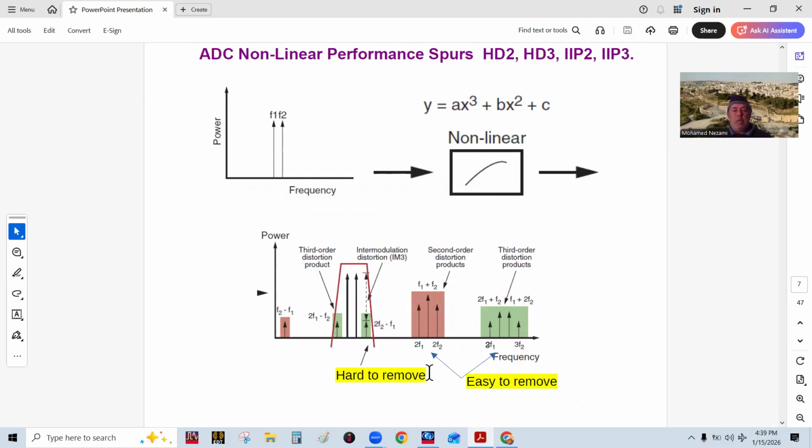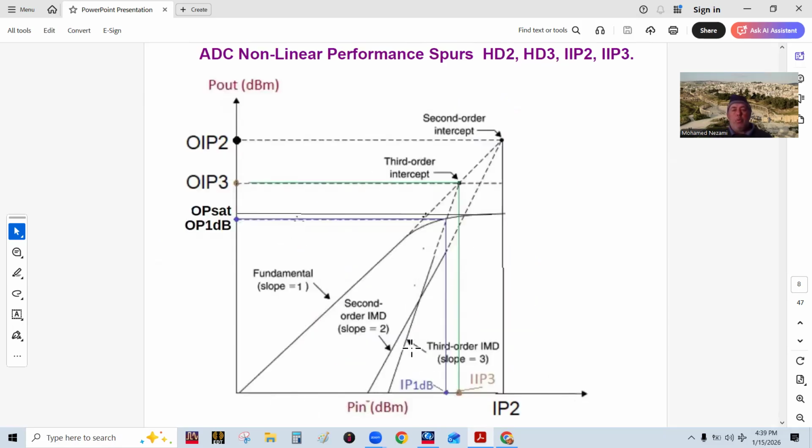and that can be observed by sweeping the input signal in here; you sweep it and you monitor the output, okay? And of course, this one in here happens to be normalized by the gain. So the power in the linear region, you've got power in, power out. Okay, so we subtracted the gain, normalized it to the gain. So what's going to happen is your input signal itself, as you push more and more signal, you're going to end up being linear until a point where it starts to clip and saturate.